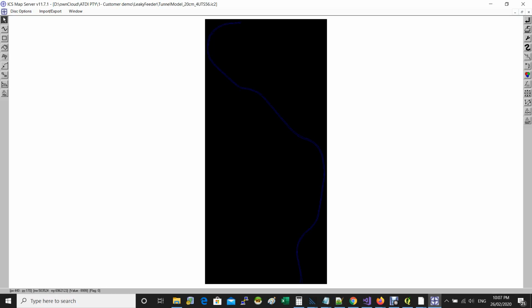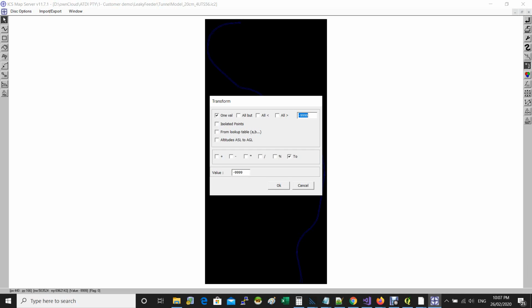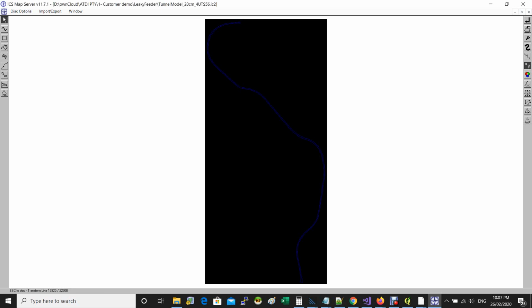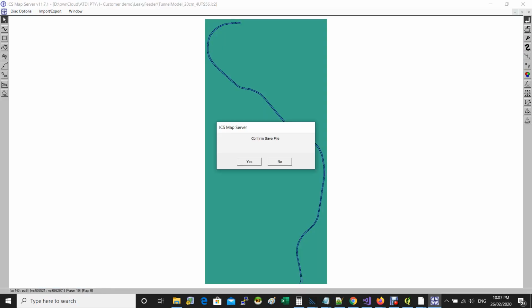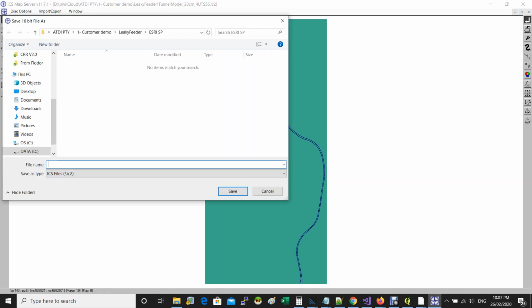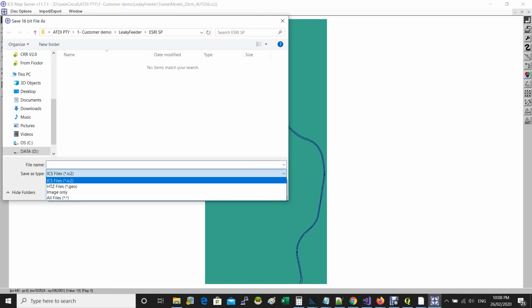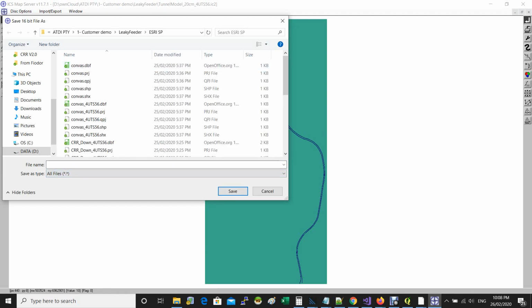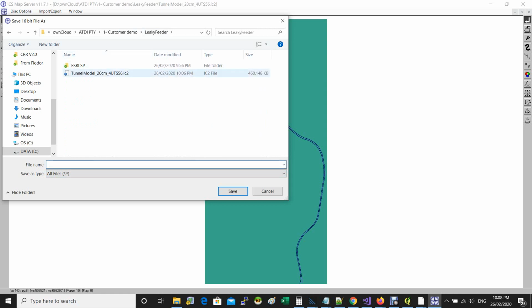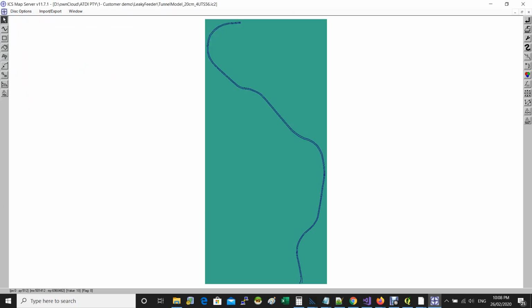Now for indoor modeling, I advise you keep the 0 as 0 and then the minus 999, you change it to 10. 10 means non-penetratable. So I hit OK. Now you see, this is open, this is 10. So you save now. You can save it as any format. I would advise you to save it as a different extension, ATDI indoor raster. Save, done.